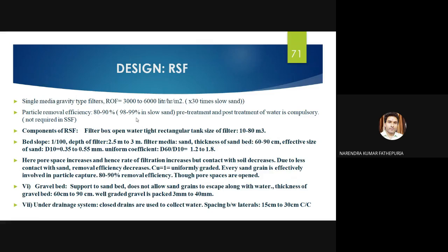For uniformly graded particles, the coefficient of uniformity will be equal to 1. Every sand grain is effectively involved in particle capture, with 80 to 90% removal efficiency, and the pore spaces are open. These are all the constraints for this rapid filtration.